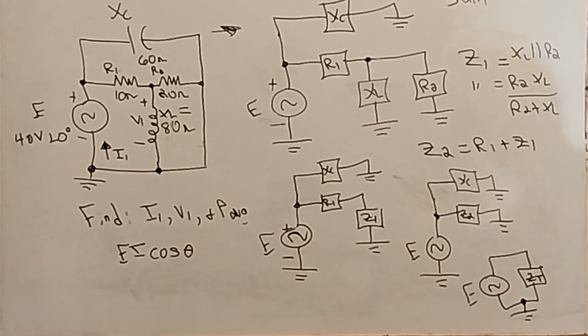If you have two voltage sources, for instance, in superposition, you short one, and you're going to use the other to do the analysis first. Then you short one voltage supply, do the analysis, find the total current, voltage drops, and do the same thing again with the other voltage source shorted. But if you have a current source, you've got to open those. So if you have a voltage source and a current source, you can still use superposition, but you're going to open the current source and let the voltage source run, and then the voltage source will be a short. So that's good to remember for superposition.